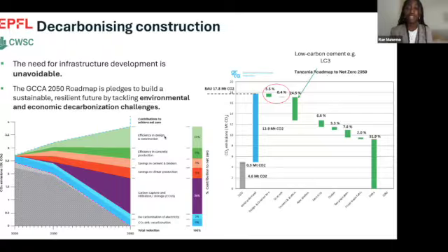And as you can see, for a country like Tanzania, low carbon cement or lower clinker cements are much more accessible due to the availability of materials such as clay, which can be added into cement for making a new blended cement called limestone calcined clay. But then I've also highlighted the two levers, which are design and construction and concrete, which when we make this roadmap, it's in interaction with the cement producers and key role players in the industry.